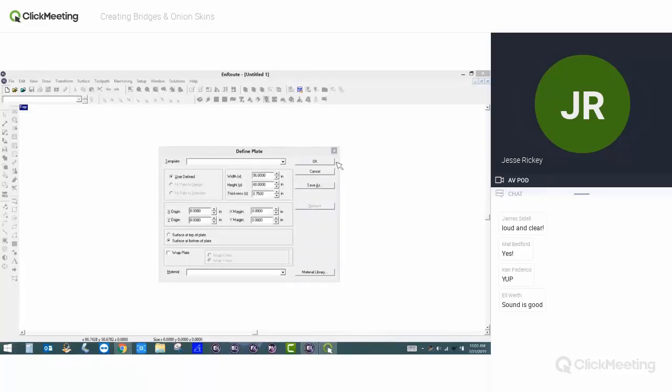However, before we get started with that, I always like to go over the define plate just a little bit because it's very important, especially when it comes into tabbing and bridging a part. For instance, if I am surfacing the top of the plate and I'm working down to my spoil board, your thickness does become really important because we're going to cut all the way down to the bottom, and our bridges and our tabs, we're going to start from the bottom of the toolpath.